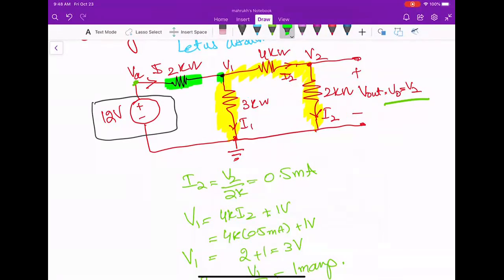Am I right? Yes. Because whenever you, let's say, apply nodal analysis here, you always say V1 minus 12 divided by 2, right? So it means that this VA is actually equal to the voltage drop here plus the voltage here, because the voltage here is the same as the voltage in this branch and this branch. So there is no further voltage we have to add.